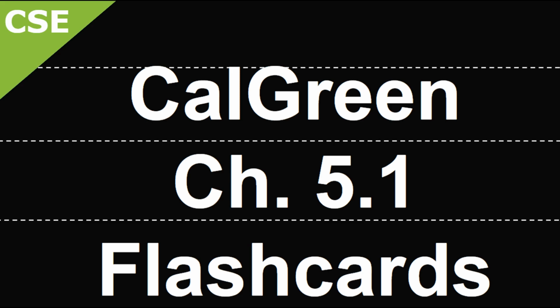Let's discuss the regulations that refer to levels of standards for chargers. Let's understand the difference in each level and the terminology. In CalGreen, you'll see the terminology of level 1 EV charging receptacle. A level 1 EV charging receptacle refers to an electric vehicle charging station that has electric vehicle supply equipment that's rated at a 120 volt, 20 amp minimum branch circuit and receptacle.